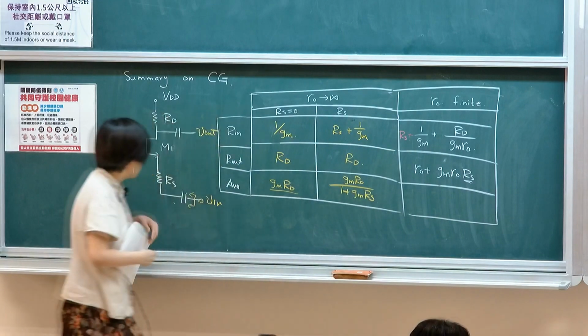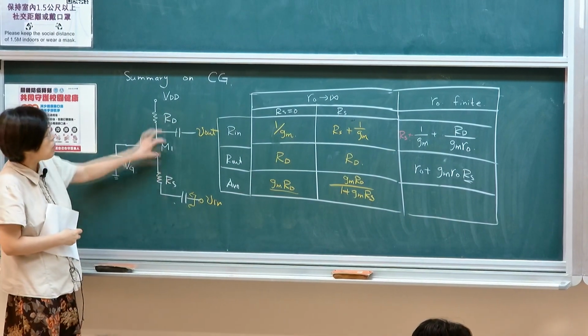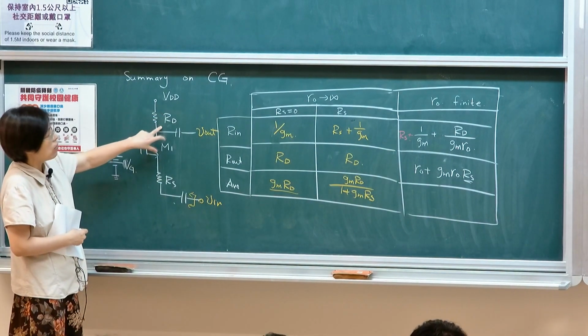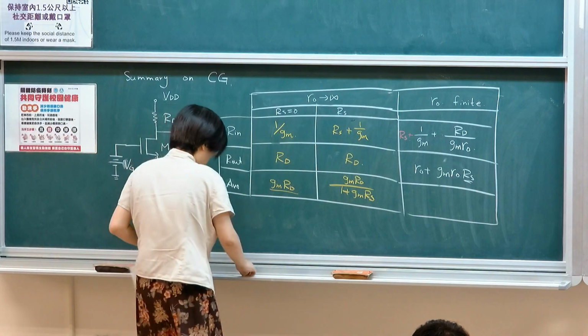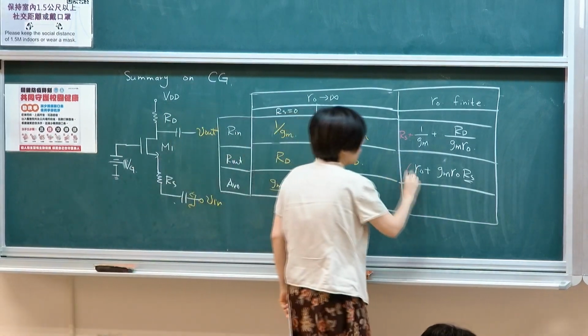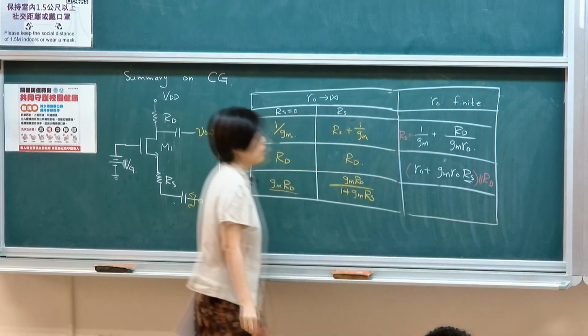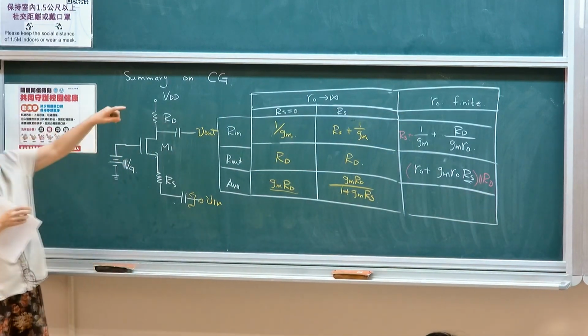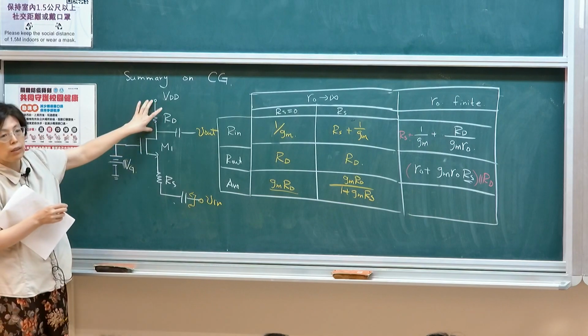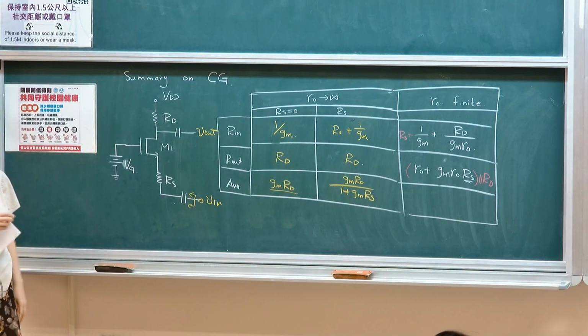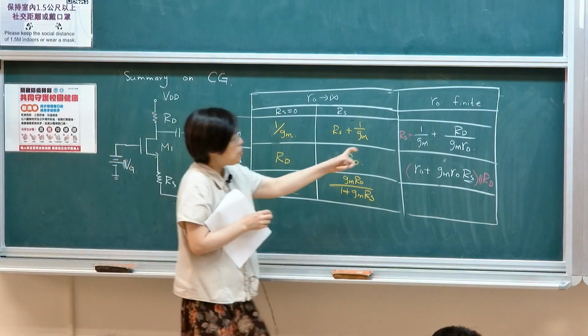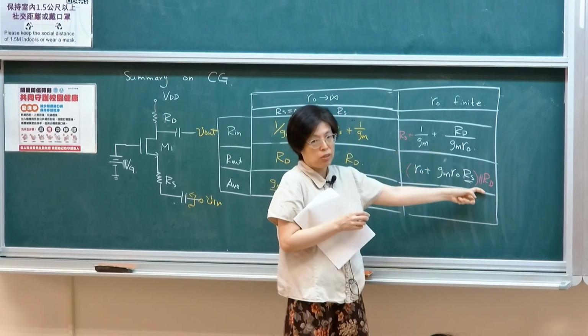So the resistance looking down, the source resistance, is being amplified by a factor of this. And if you want to include RD to be more precise, it will be the resistance looking down, RL, in parallel with RD, which will be your ultimate resistance. This will depend on whether you want to add external resistance.